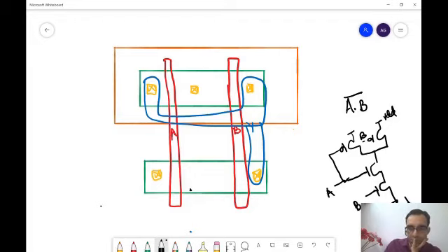One is the source and drain. We get an NMOS, right? So we get a source and a drain there, and this is another NMOS. And by virtue of shared diffusion region, shared active, this connection is already being built there. Am I right?